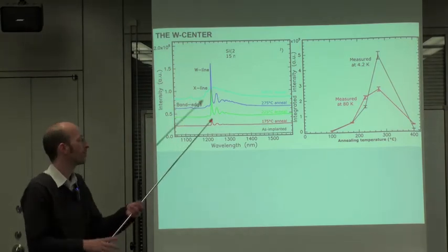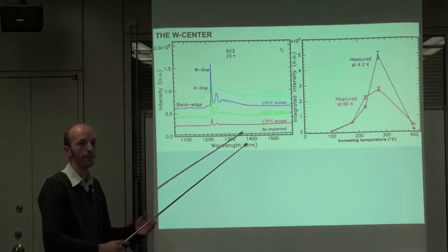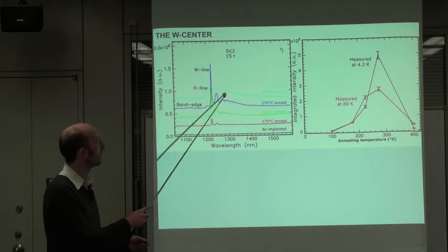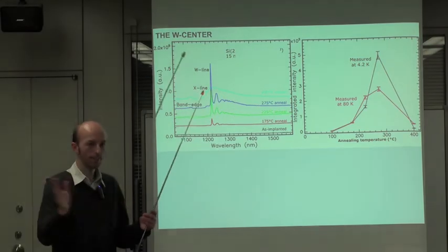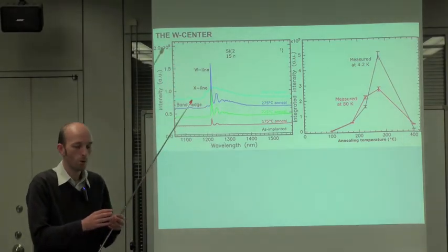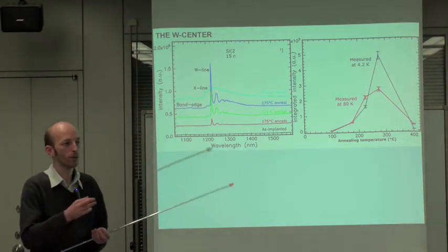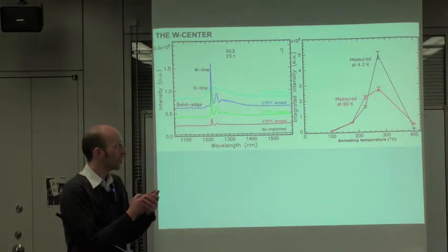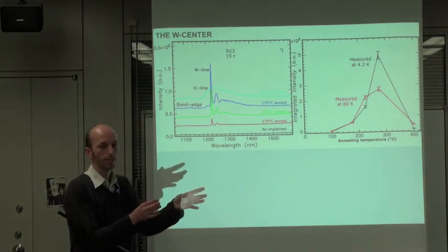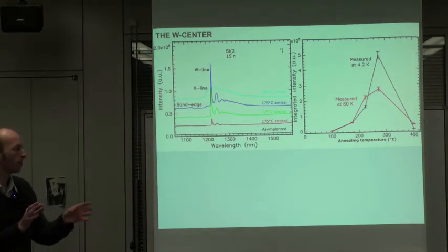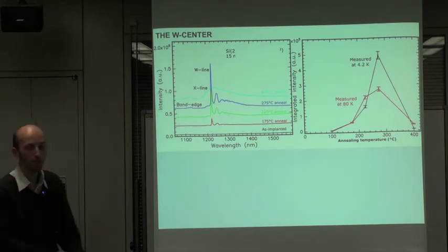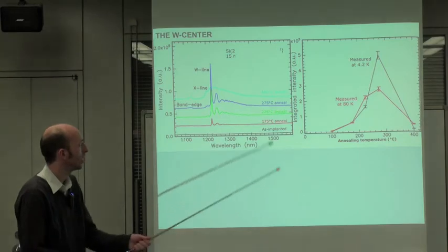It's not very stable. It just requires a 270 degree anneal to form it. So for higher anneals, it disappears. More complicated structures are formed. So for example, the W center is thought to be a precursor to dislocations. So a W center becomes a 311 type defect with higher temperature anneals.